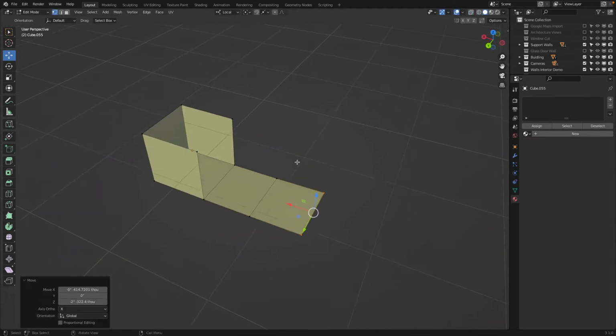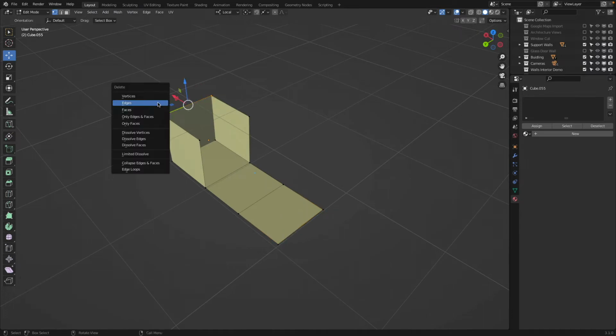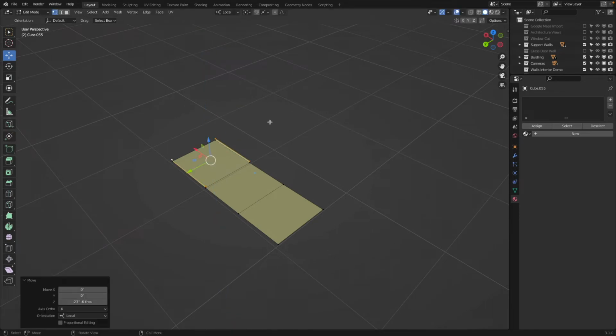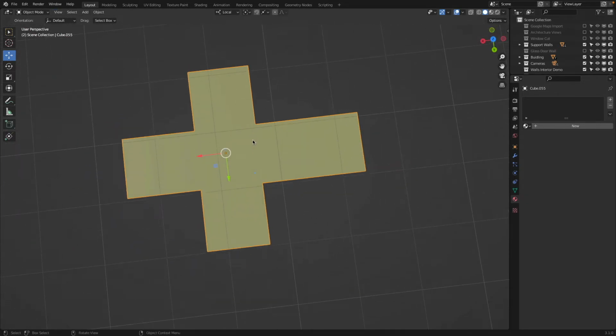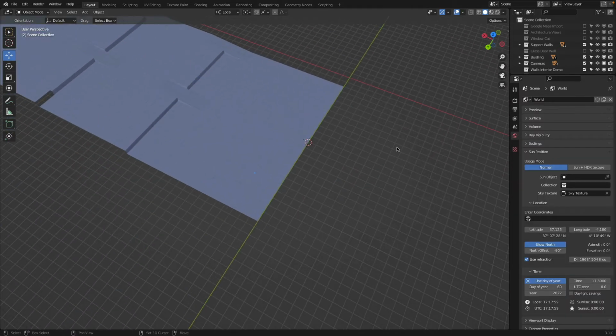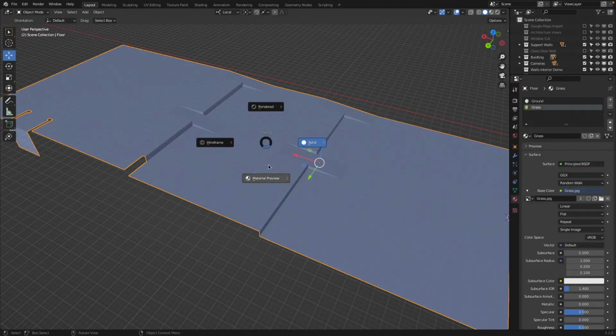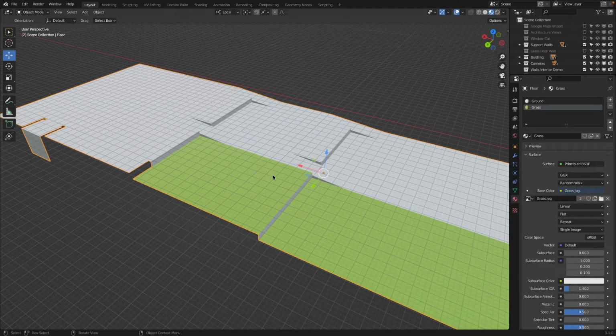So see this? Because if we do this actually with everything, so all edges, then we will end up with a nice two-dimensional pattern. And onto this pattern now I can project my two-dimensional image, and then the software can take that two-dimensional image and project it onto our three-dimensional geometry. So UV unwrapping. Think about UV like X and Y. So how does this work?